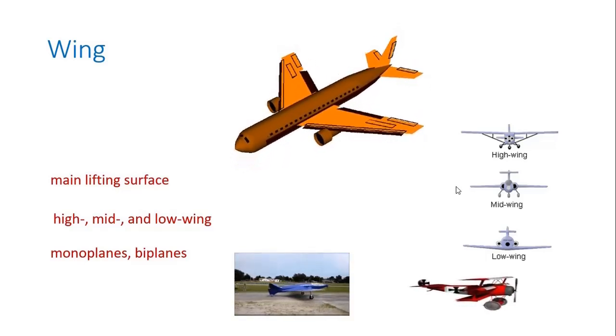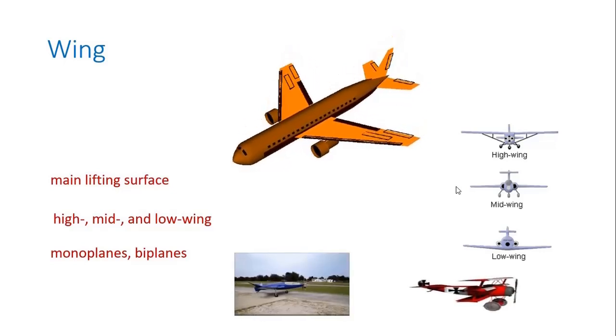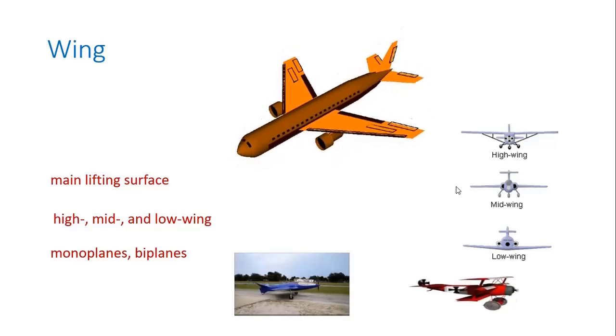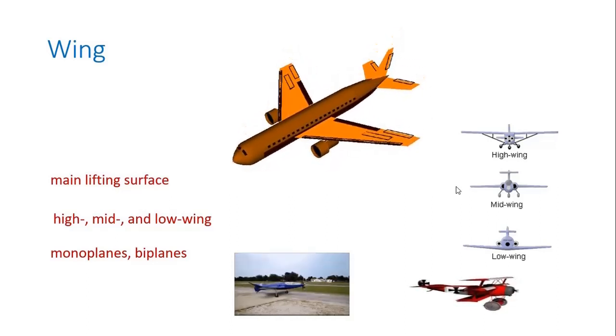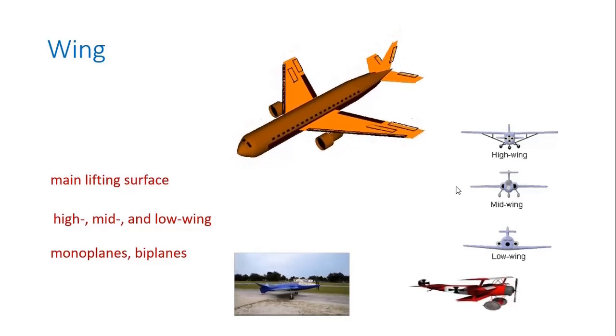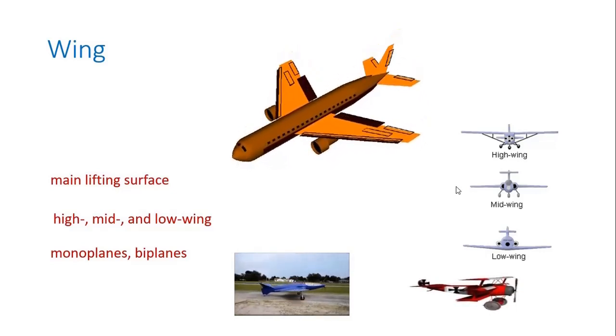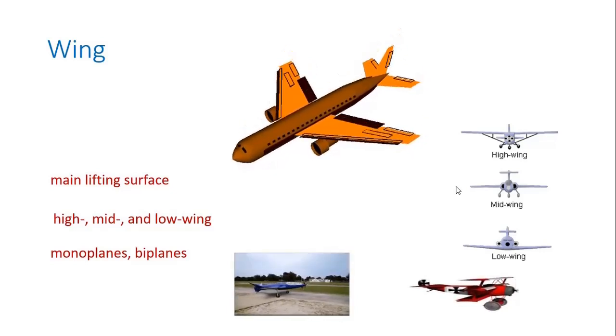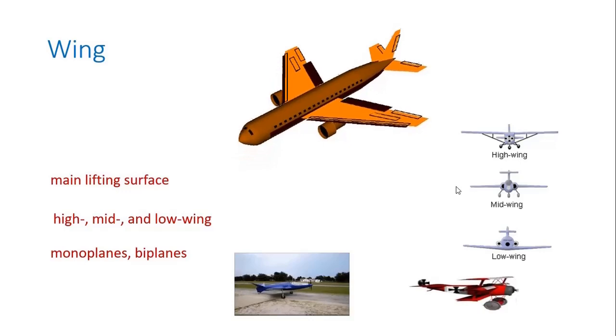Since the wing struts are usually attached approximately halfway out on the wing, this type of wing structure is called semi-cantilever. A few high-wing and most low-wing airplanes have a full cantilever wing designed to carry the loads without external struts.